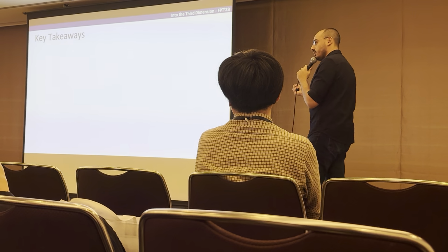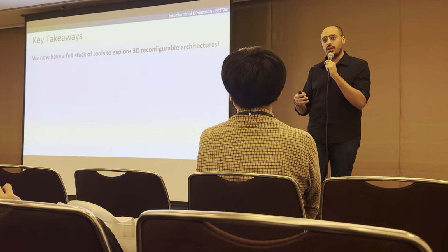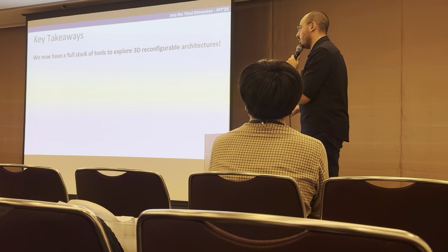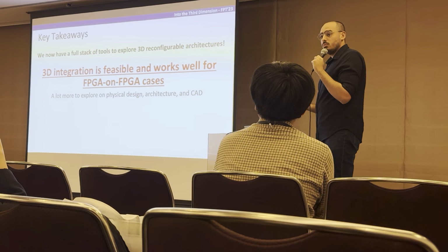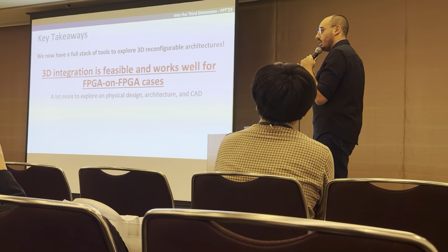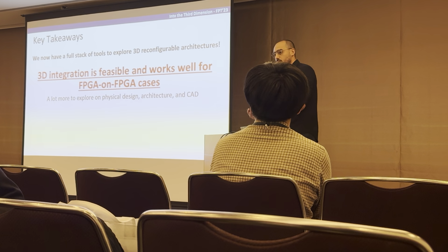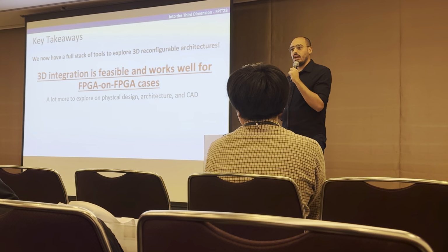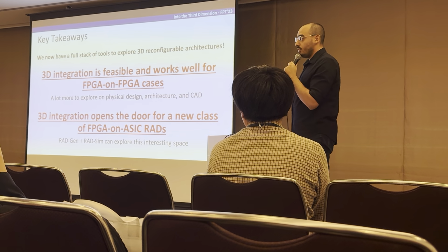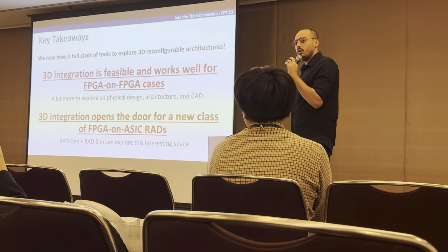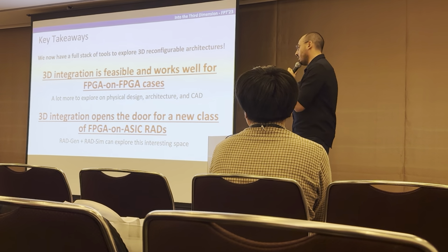Okay, so what are the key takeaways of this talk? We now have a full stack of tools that can help us model those 3D reconfigurable architectures. 3D integration is feasible and actually works well in the case where an FPGA is integrated on top of another FPGA, but there's a lot more to explore in terms of the circuit design, the architecture, the CAD, and how to make this work better. 3D integration also opens the door for a completely new class of devices that integrate FPGAs on top of ASICs. And we have tools to model that.